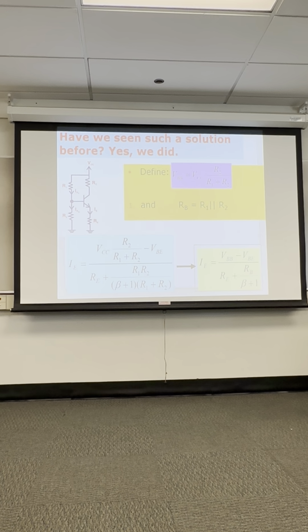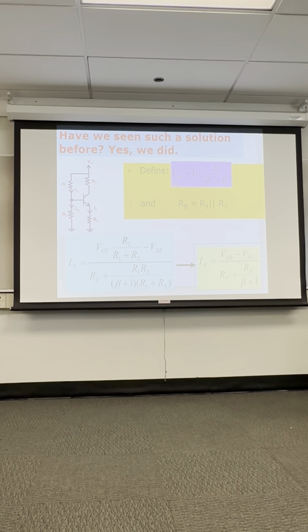We'll assume the resistors are given. So here are the equations for solving the circuit we're setting up. V sub B is sometimes just called V sub B. Doesn't always have a B. This is the voltage on the base here. And is this equation correct? What does this equation imply about the circuit? A voltage divider, and what else?